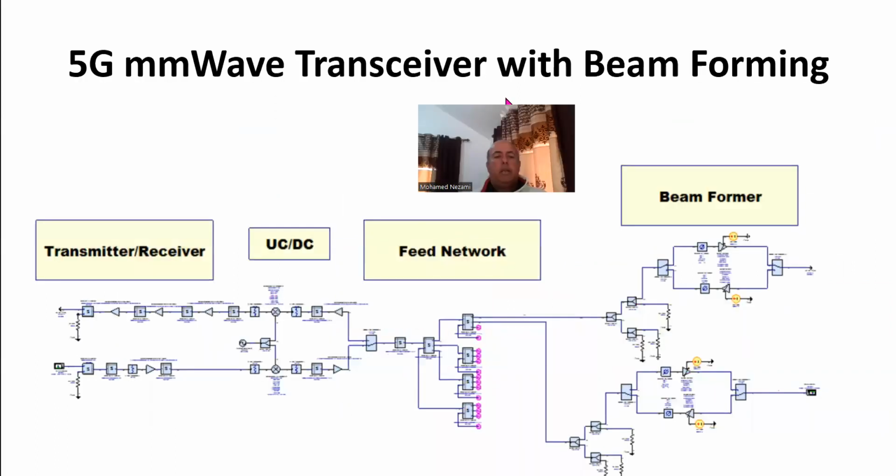This is basically the top level diagram. We've got the transceiver section in here that is running at 3.5 gigahertz. We've got the up converter and down converter section in here, which runs using a 24 gigahertz LO to either transmit or receive at 27.5. Then we've got the transmit receive switch in here. We've got another filter in here, one of these off-the-shelf filters, just to make sure that my signal is clean and reject all the spurious and harmonics.